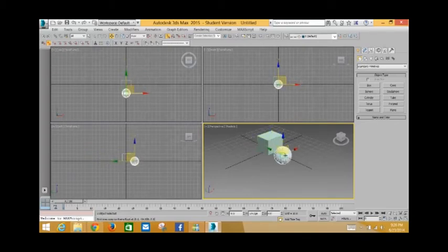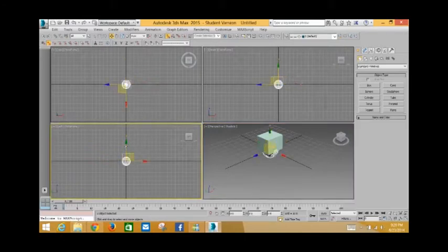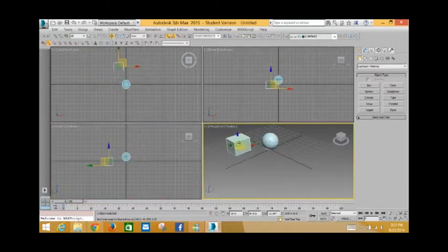You'll probably always want to have that fall more on the ground plane, like so. You can see I've got my snaps on here. I've got my 3D snaps toggle, and I'm going to go ahead and cut that angle toggle on, which will allow me to rotate items. And when I rotate them, they can snap to whatever I want them to snap to.